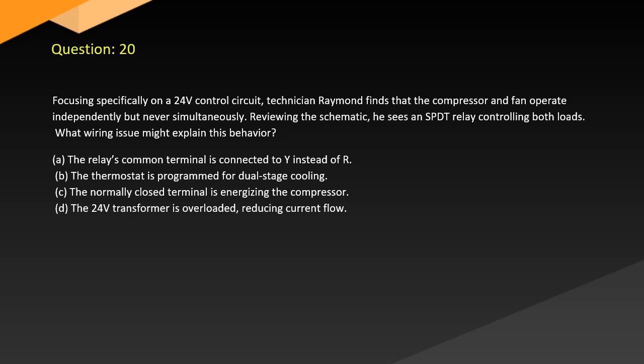A. The relay's common terminal is connected to Y instead of R. B. The thermostat is programmed for dual-stage cooling. C. The normally closed terminal is energizing the compressor. D. The 24V transformer is overloaded, reducing current flow.